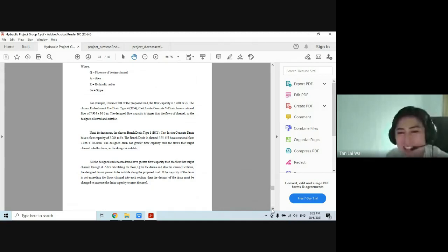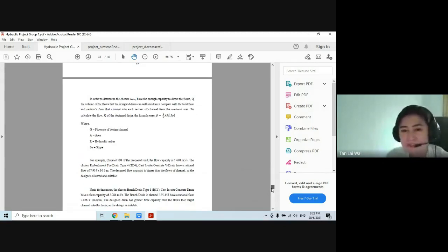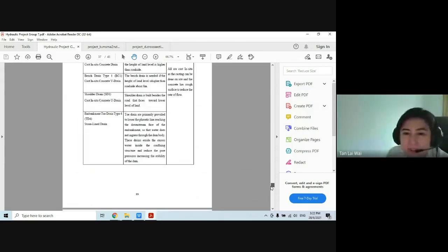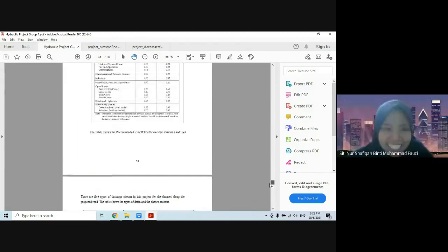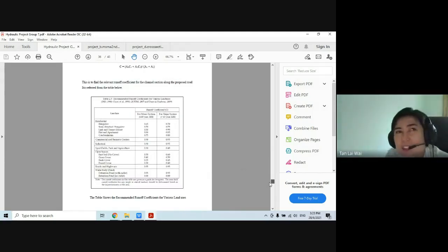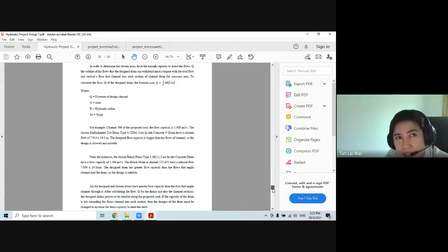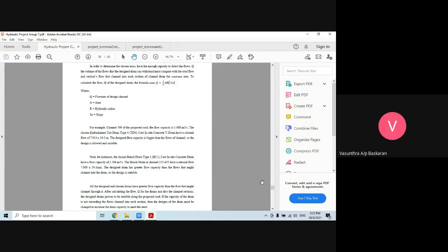Alright. Did you check the velocity? As I said, if using an earth drain it should not exceed 2 meters per second, and if using a concrete drain it should not exceed 4 meters per second. Did you check that? Concentrate is there. Which one, doctor? Sorry, I don't get you. There is actually a sort of limitation to avoid sedimentation and to avoid going below 2.0 meters.